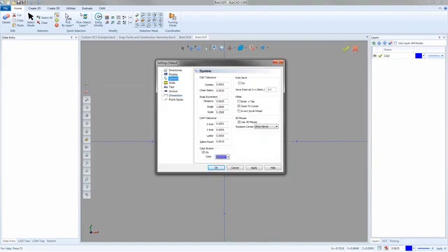So over here, I just want to talk about the System tab real fast. This is where we find all our tolerances, snap increments, cam tolerances here, autosave. For those of you that haven't gotten into the mode of just hitting save as often as possible, autosave is here for you. So you go on, you say, I want to do an autosave. The minimum's 15 minutes. So the lowest you want to go with your save interval is going to be 15 minutes. You won't go any lower than that.